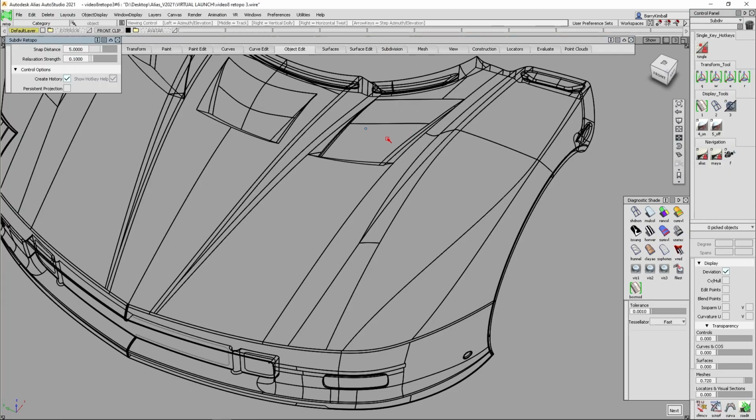And if I had a surface model that I wanted to retopologize, and why might I want to do that? I might want to make a lightweight model of an existing surface model so that I could do some quick proportion changes. A lot of designs are based on a previous design, and to begin to go in and start moving all these surfaces around individually can be a lot of time consuming, can take you a lot of work. So this is just a method for you to be able to quickly build surfaces over top of an existing surface model with Subds. So I'll again go into the Subdivision Retopology command.